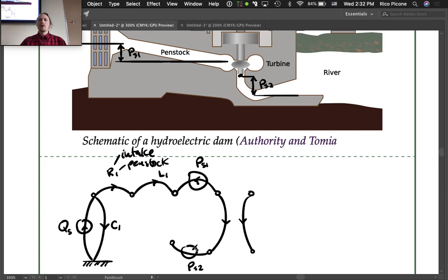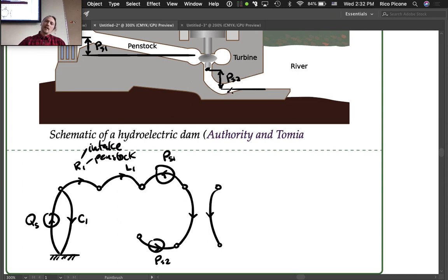And so we also have to think about which direction this arrow is going to go. The pressure is once again going to be higher down here, and so it's going to drop that direction. That arrow is not super clear. And then we've got, it's hard to say. This might be long enough. We don't have dimensions here, but this doesn't look like it's super long and the fluid's all flowing in the same direction. So maybe we'll ignore the inertance here. Say there's going to be some resistance associated with going around this curve and then this outlet. So there'll be some resistance, R2.